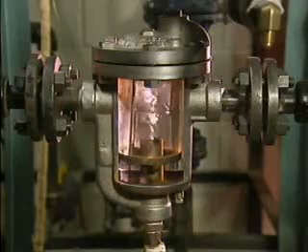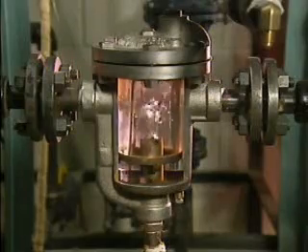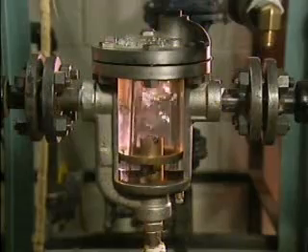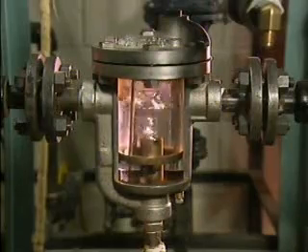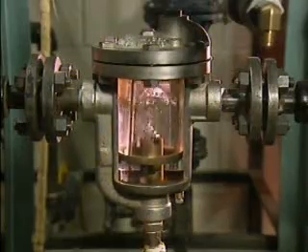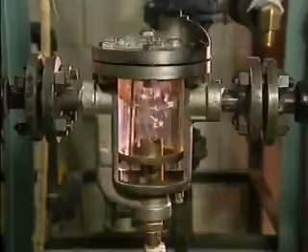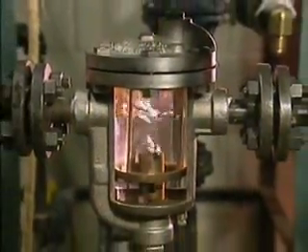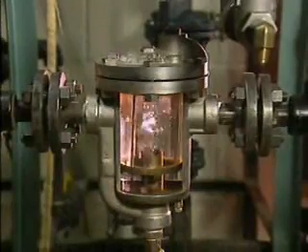The open float in an inverted bucket trap makes the trap resistant to water hammer. Inverted bucket traps are also able to handle air and other non-condensable gases because these gases are less dense than condensate. However, the vent in the top of the bucket is small, and only a correspondingly small amount of air can pass through it. So to avoid problems, inverted bucket traps generally should not be used if large volumes of air must be removed.